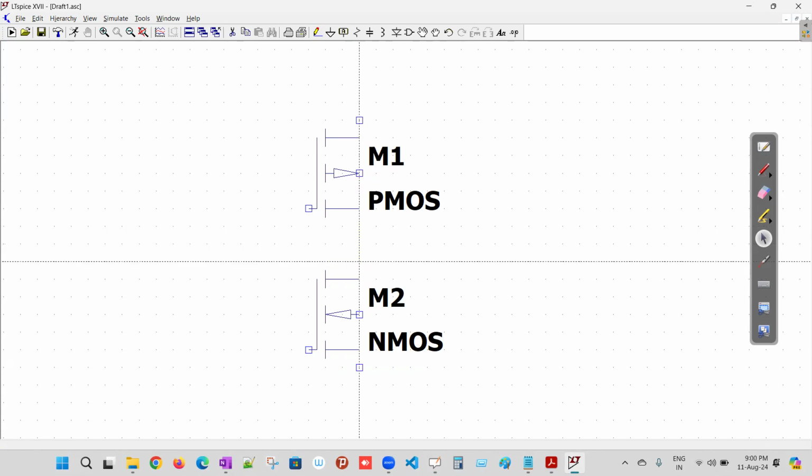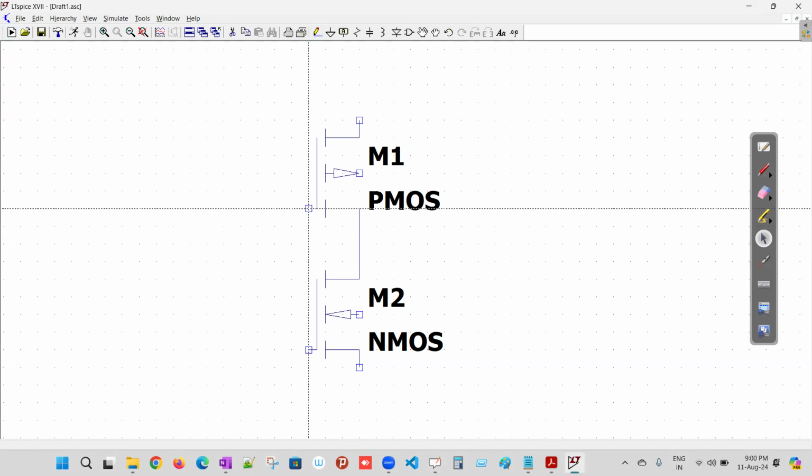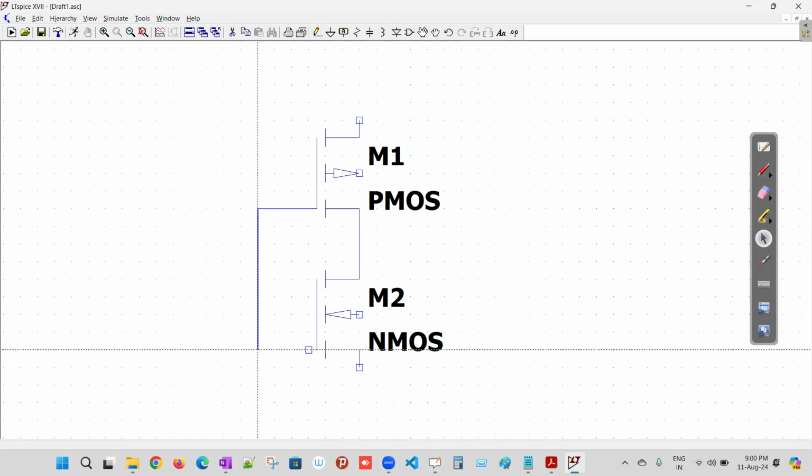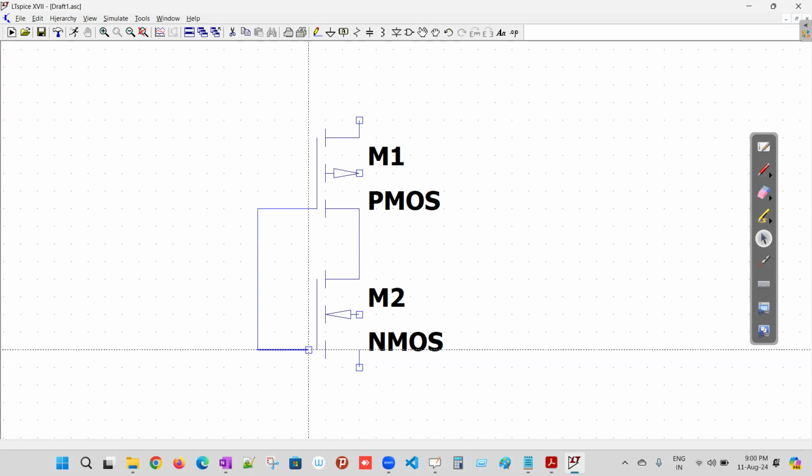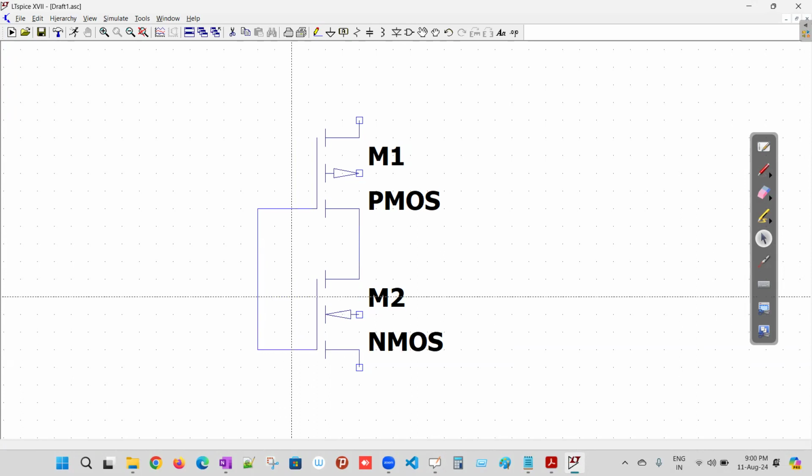So the connection is established. Now we also have to connect these gates. Let's say you wanted to take a turn from this point here. Once you click, come down here and just hover your mouse there. Then from this point, if you wanted to move in this direction, you click once, then take a direct diversion like this, then click here. That way you establish the connection.